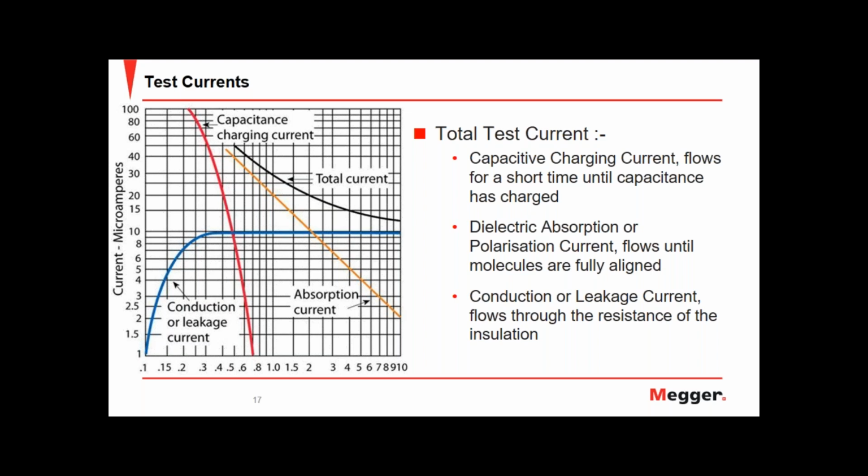So that is kind of the expected result. You want to have a very high value, and it could be in the teraohms and the gigaohms. Not always are you going to get that. But if you're getting low values and you want to troubleshoot and be sure that you are doing the right thing, and that the result is coming just from the response of the insulation inside the equipment and you're not getting any external effect, then you want to do what the person that asked the question mentioned, having the cables in the air. So that is something common.